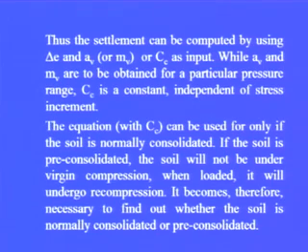The equation with Cc can be used only if the soil is normally consolidated. If the soil is pre-consolidated, the soil will not be under virgin compression. When loaded, it will undergo recompression. It therefore becomes necessary to find out whether the soil is normally consolidated or pre-consolidated.